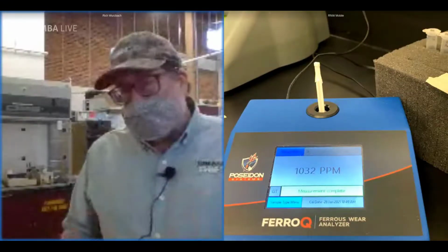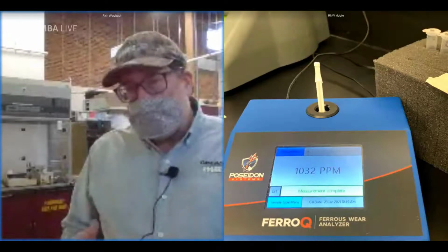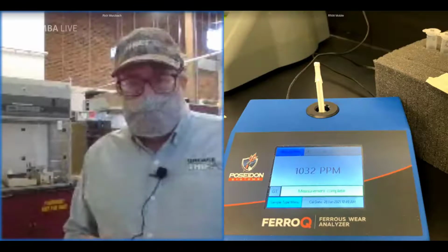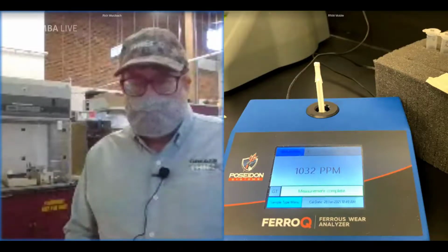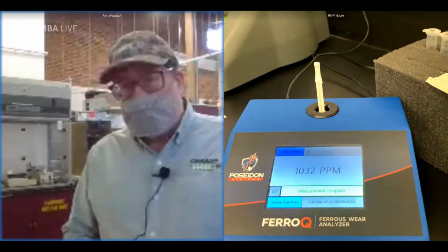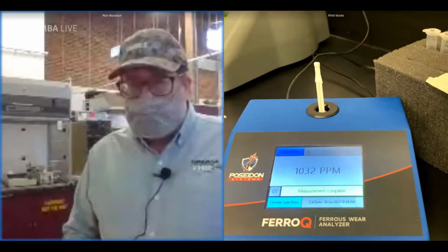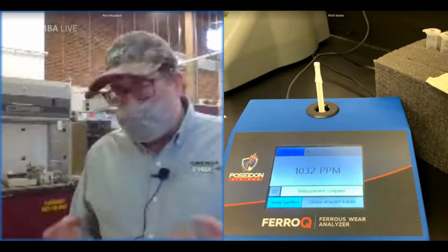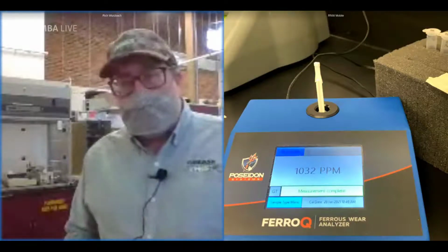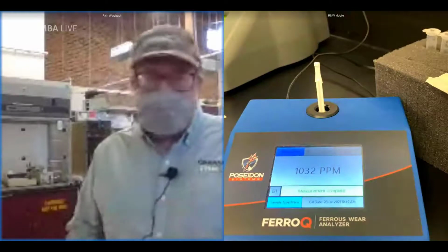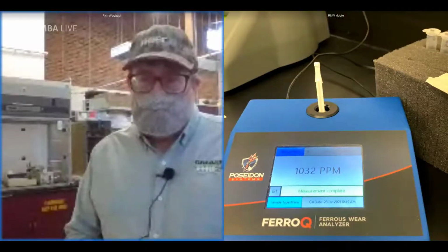So I'd say it's a combination of that, but remember that the quantity that you generate really is a function of the machine itself, but also how old the grease is, or how long the grease has been there. So if the grease has been there a real long time, just the straight up ferrous content could be fairly high, and it's just that it hasn't been replenished. So tying that into the assessment is important as well.